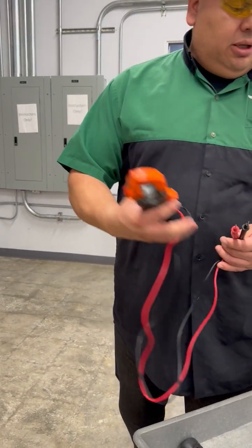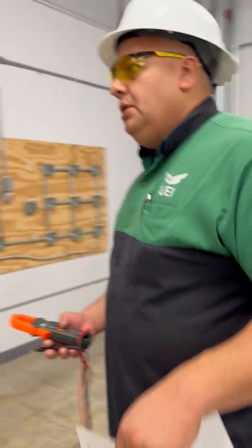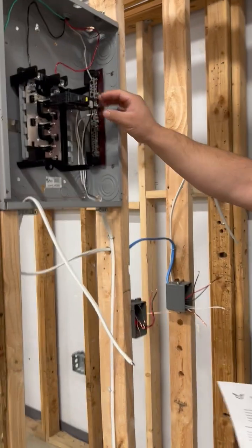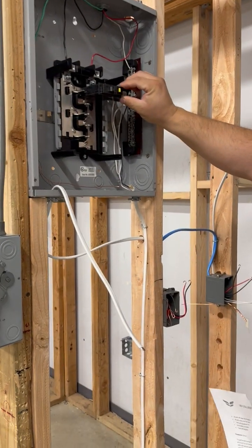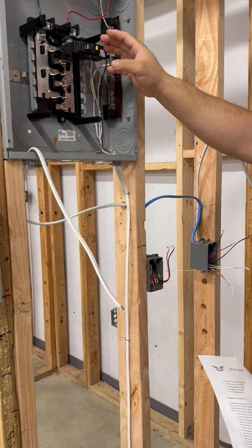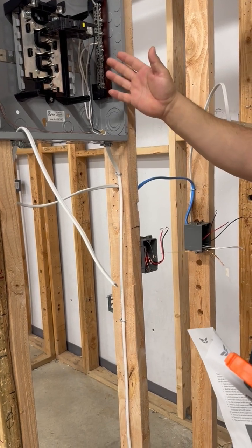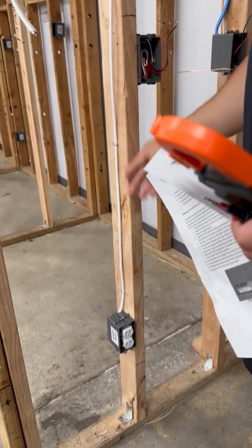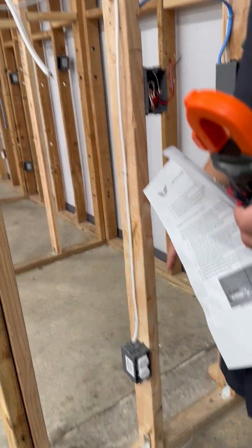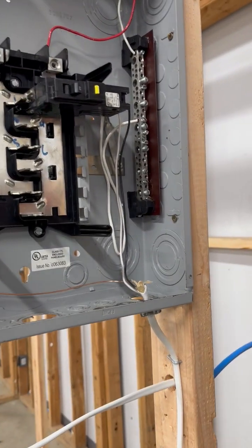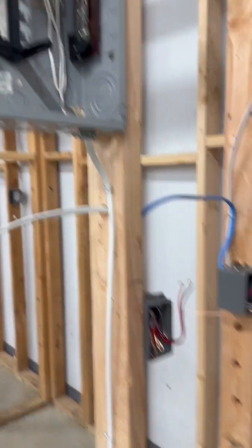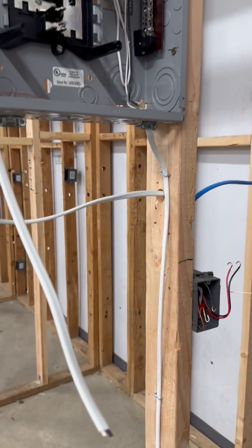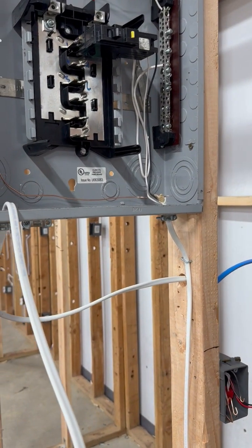As we come into the unit over here, we can see that it's been set up for an AFCI, GFCI combo breaker. It's got a circuit that starts at the panel with that protection, coming down to a standard receptacle, where that protection will be provided for the whole circuit that is attached from there forward downstream. So this is a good point to illustrate to them the code section that applies to this.